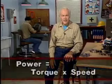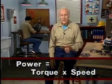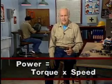Well, so far we've looked at how speed can be changed across a gear set. And we've seen how this change can be described by using a gear ratio. These ratios can be used to help determine the speed of rotation of a gear set if the input or output speed of the gear set is known. Now remember, we said that the reason gears are used in machinery is to transmit power, and the way in which gears transmit power can be described using the equation power equals torque times speed.